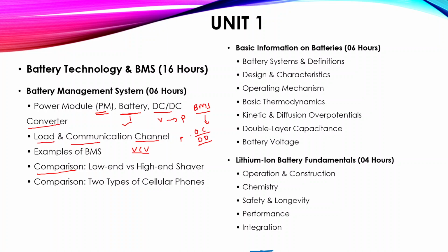Okay, in high end systems like electric vehicles, the BMS will perform complex tasks, including cell balancing, SOC estimation, SOH prediction, and advanced fault diagnostics. Thus, the BMS complexity depends on the application requirements. So, whenever we are designing the BMS, we need to see for which application we are designing it.